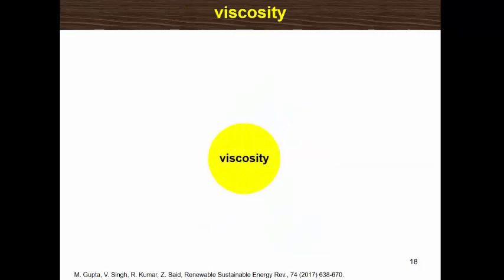Viscosity is an important property, particularly concerning fluids flowing in a tube in a heat exchanger, because the pressure drop and pumping power depend upon it. In this regard, many investigations have been carried out to determine the empirical and theoretical correlations for the estimation of viscosity of nanofluids. It should be noted that most of the instruments that have been used for measuring the viscosity of nanofluids were developed and calibrated using homogeneous fluids.